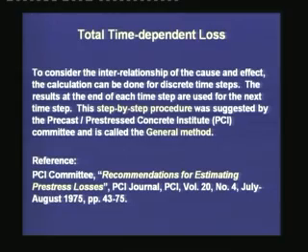That means the basic idea is that we have discretized the service life into several time steps, and we are calculating the loss at the end of each time step by assuming that the prestressing force is constant over that time step. Once we have computed the loss at the end of one time step, we are recalculating the prestressing force, and that new value becomes effective for the next time step.